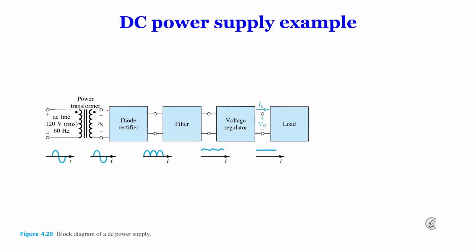A typical rectifier circuit consists of a couple of stages. You will have a transformer on the AC side, and you transform that AC from a high voltage to a lower voltage, and then you get a smaller AC, and you rectify. And then after rectifying, you do filtering, so you get rid of the ripple. After the filtering, you get a certain DC, but it's not a constant DC, because it changes if the AC input changes. But for a lot of applications, you want a stable, fixed voltage.